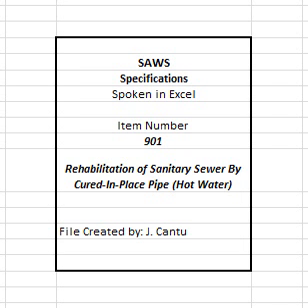E. Wrinkles in the finished CIPP that reduce the structural integrity of the CIPP are unacceptable and shall be removed or repaired by the contractor at no additional cost to the owner. 1. If a void between the wrinkle and the pipe exists, the contractor shall repair or replace that section of the pipe at no additional cost to the owner. 2. Methods of repair shall be proposed by the contractor and submitted to the engineer for review and approval.